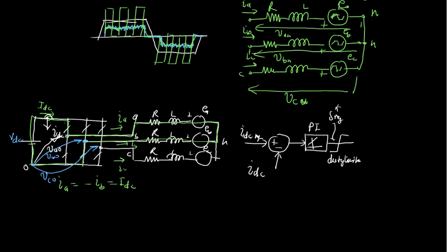When the switch is off, what will happen? Please remember, this is an inductive load. When the switch becomes off, the body diode of the lower switch will start conduction. Nowhere have I drawn the diode, but you remember that in the previous diagram I drew diodes. If you have an inductive load, you cannot bring the inductive current down to zero, because current through an inductor relaxes the voltage across. It will not make it zero.